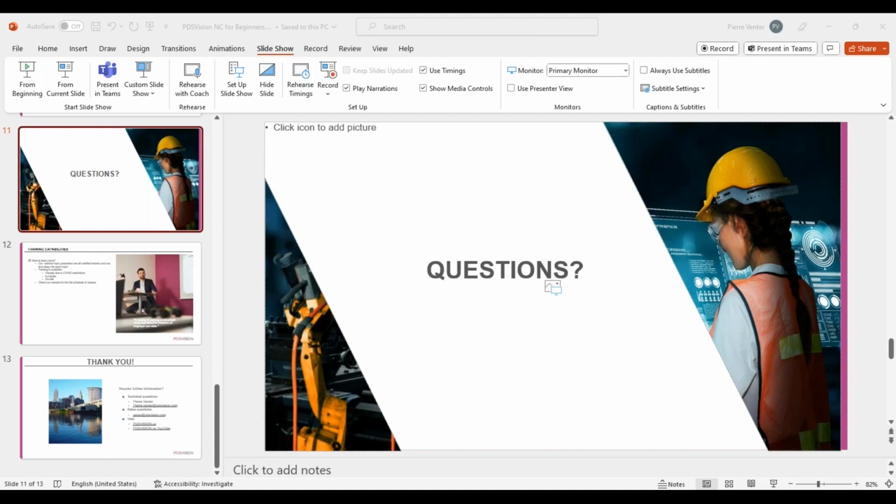It's not going to use the tolerances. It's going to be a perfect scenario, like with any other design in Creo. If you say a hole is 5 millimeters, then that hole is 5 millimeters. We all know on a machine that's going to be different. But no, Creo is not calculating for those tolerances when it's generating your tool paths.